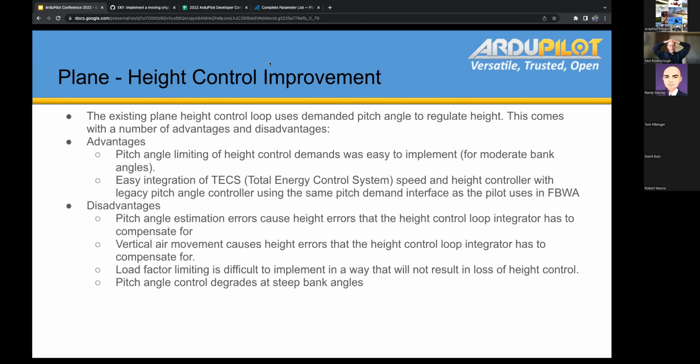It's also the other surprising thing, the calibration on the magnetometer. I tested the same plane with airspeed and compass. Then I tested it with just compass, no airspeed. Then I tested it without compass or airspeed, so it was initializing with GPS only, and then I did dead reckoning. So when I was dead reckoning, all I had was the IMU and baro, and that was it. I had no compass, no airspeed. And the results in terms of dead reckoning performance were very, very similar. It was slightly worse without an airspeed and compass.